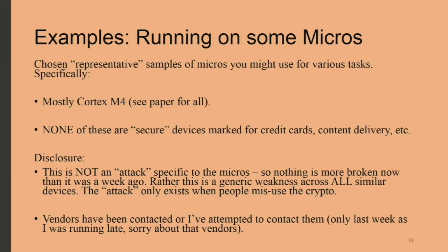And it's not an attack specific to these micros. So I've talked to these companies about it, and they were often well aware about these attacks. They have people that do this type of work themselves. One of the problems is that customers aren't asking for protection against these attacks because they might not actually care about them or know about them. So the attack really exists because people misuse the crypto core. They take a device that shouldn't be used for really secure key storage, and they just use it anyway and say, that's fine. We'll just use that same key everywhere.